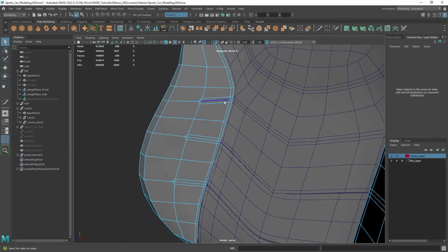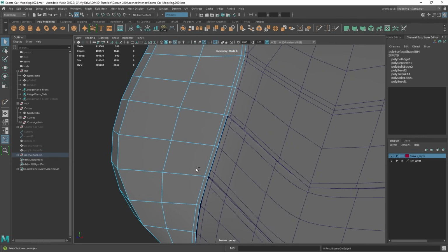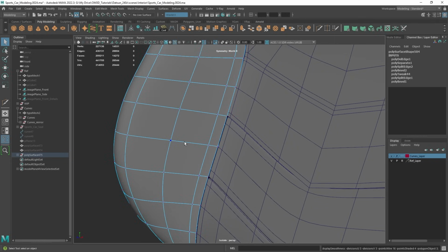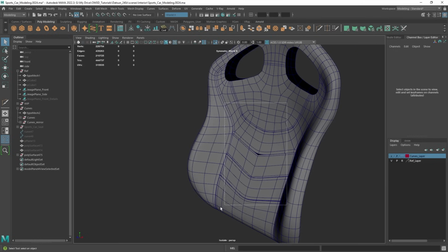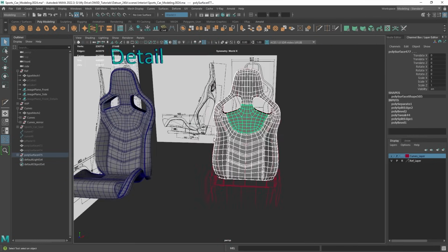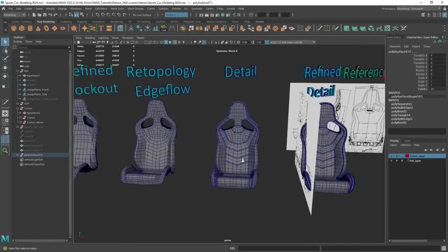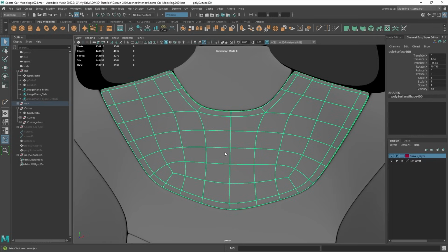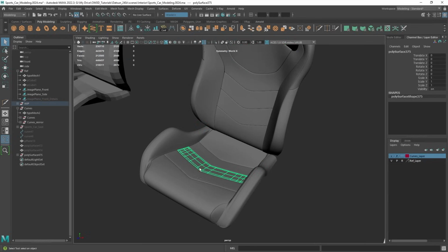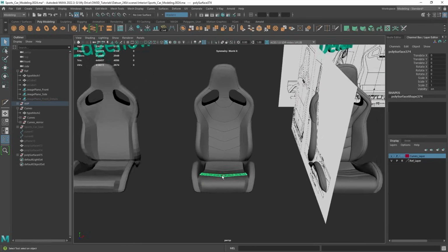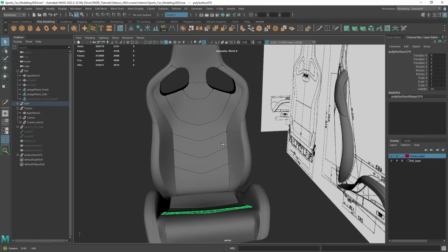I did that so it keeps everything clean here, which is part of my paneling process, and I can simply Control backspace once I have those selected, hit 3, make sure I clean up any vertices, and there you go. Okay, so that is what I used for this process here, which is this detailing process. Okay, and I use that throughout the entire model and separated it all and went by very, very nicely.